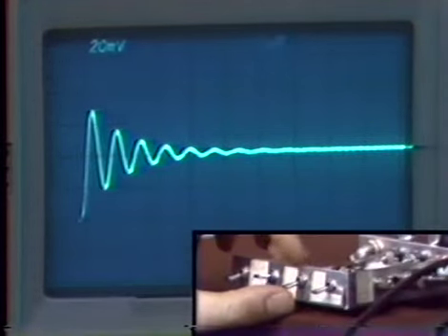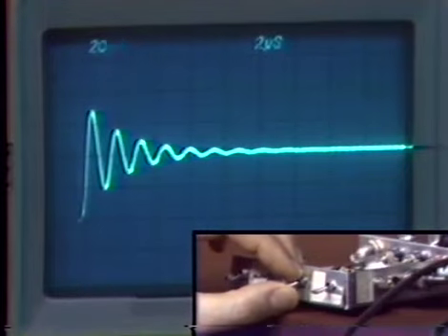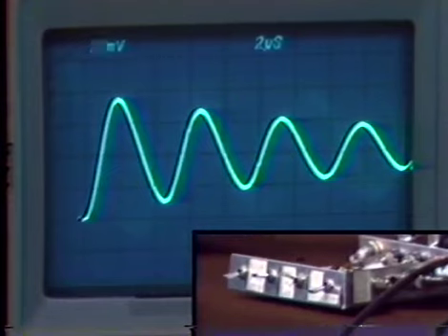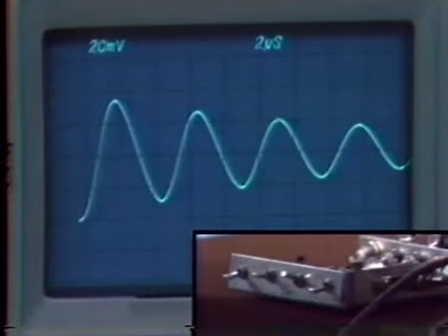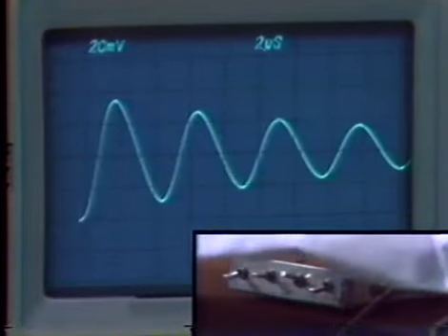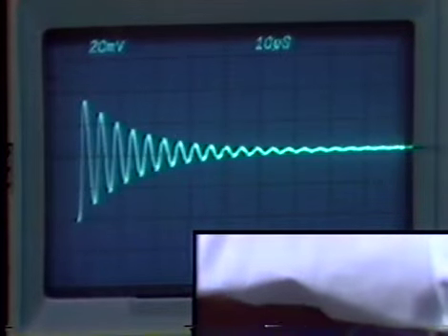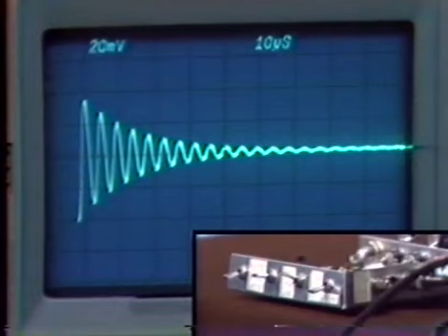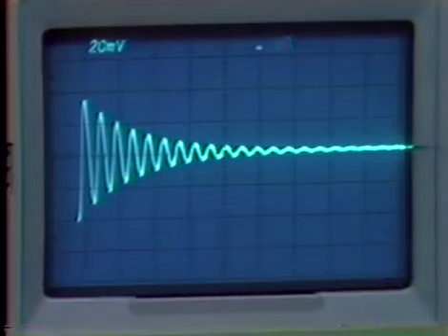Let me load the amplifier with a 1/10 of a microfarad capacitor. When we do that, we'll have to slow down the signal generator just a bit. Here again we notice a further deterioration of relative stability, considerable overshoot. We're now at 10 microseconds per division, and we notice that the response still is wiggling 100 microseconds later.